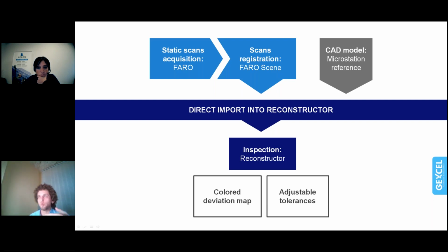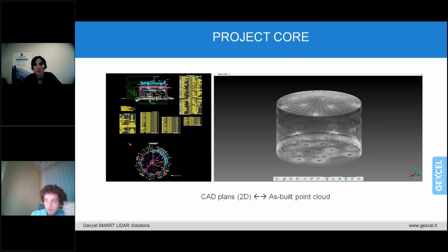So pretty much what we have to achieve is put the planned data and the as-built data on top of each other, and extract the geometry deviation data in the best visual way, because on this kind of surface, even if you measure every 2 by 2 meters horizontally and vertically, you will not get the whole image. You just get a few extractions, but the general image you will not have. And this is the point where Reconstructor came in for us.